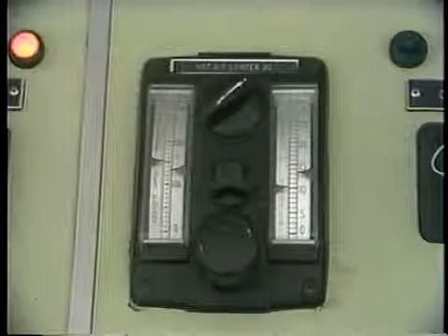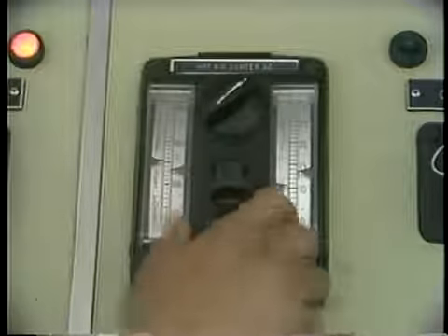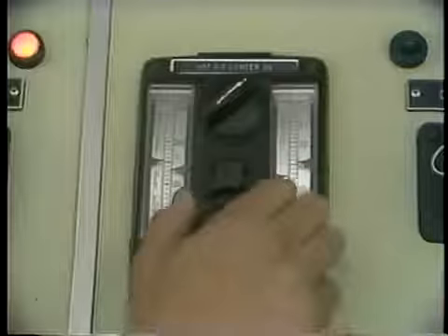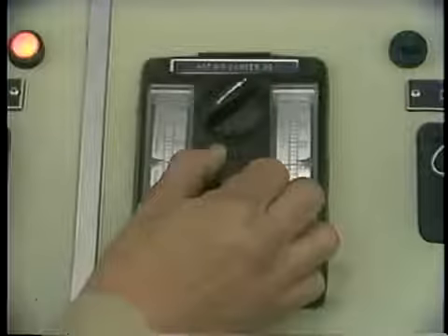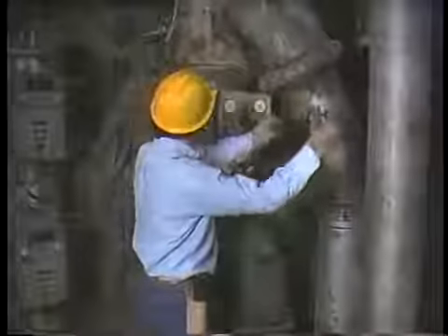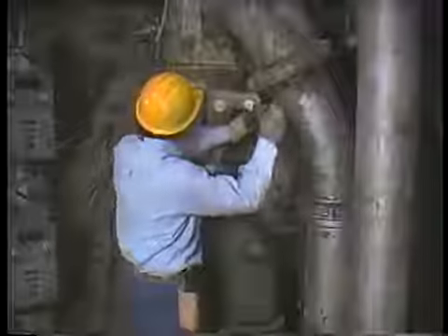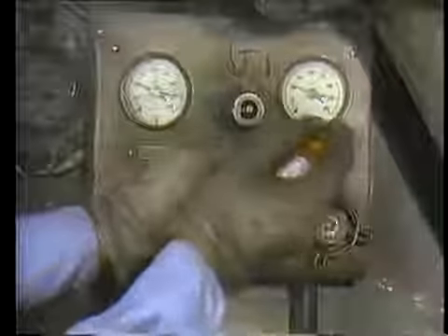An alert operator should recognize operating conditions where there is a potential for a loss of flame and take appropriate action to minimize the chances of it occurring. In some cases, this action may require increasing the flow rate or temperature of primary air going to the pulverizer. In other cases, additional igniters or a warm-up burner may be used to ensure proper combustion.